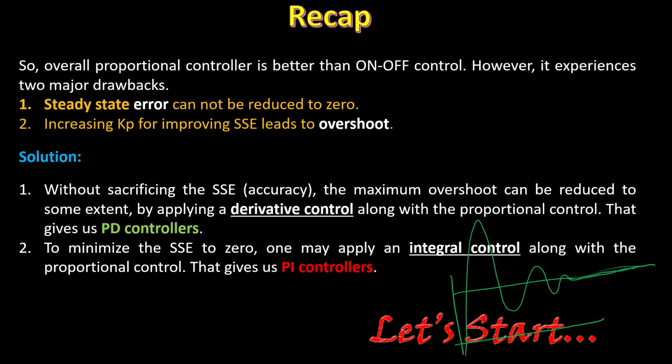It definitely depends on the application. If we can tolerate some amount of error, then we can go for a PD controller, but if we cannot tolerate any error, that means the error should always be exactly zero, then we should employ a PI controller. In the next few slides we will study the PD controller and the PI controller, how they can be realized, and then eventually we will start the PID controller.